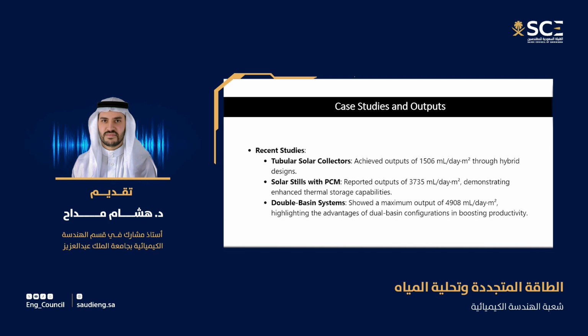Some of the recent studies also used something called PCM. PCM means phase change material. The phase change material, these are the material which can change its phase from solid to liquid or liquid to solid from absorbing the heat. These are very great material for thermal storage. They can store the thermal energy, and they use it inside the still or inside the basin.